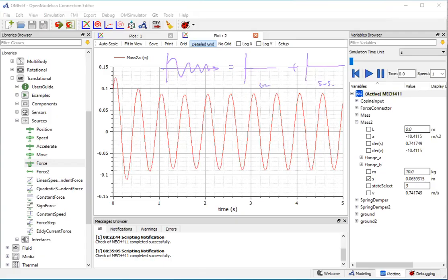Now the transient response was related to the e to the minus zeta omega n t part, the exponential decay, and you had sine omega t plus phi. Hopefully I remember this correctly. This was for the transient response. And then you had your steady state response, right? It was the second part of the whole system response.